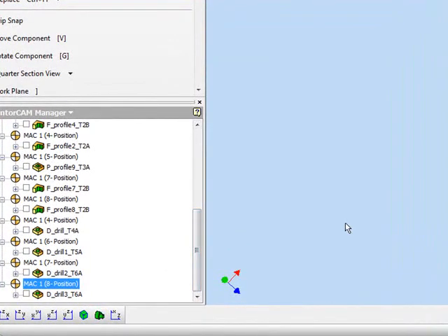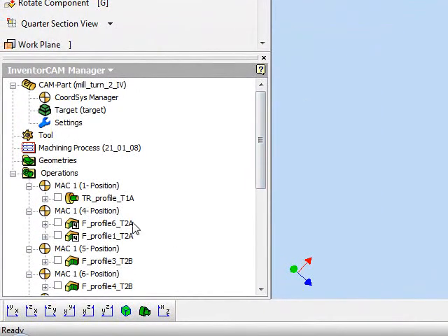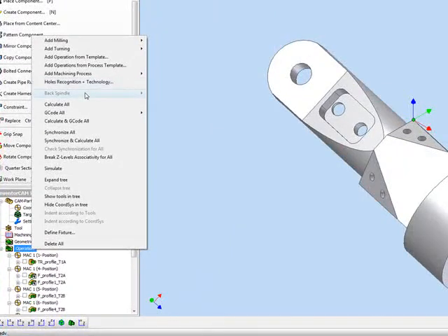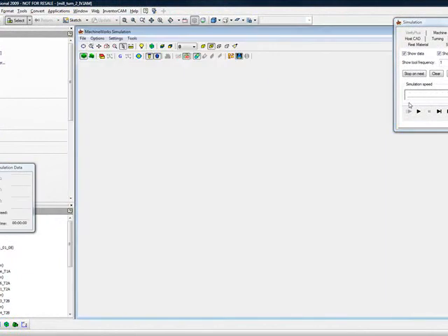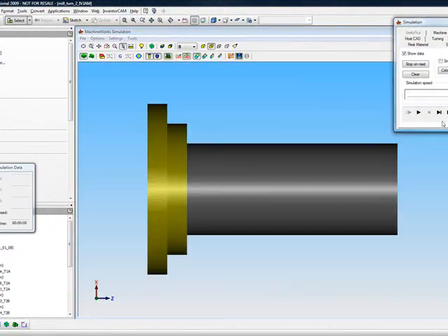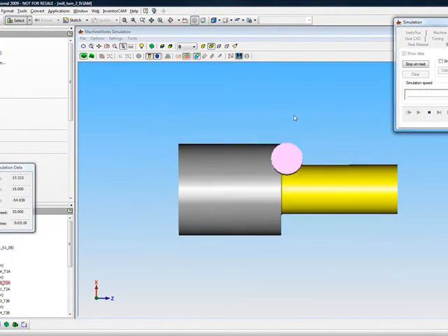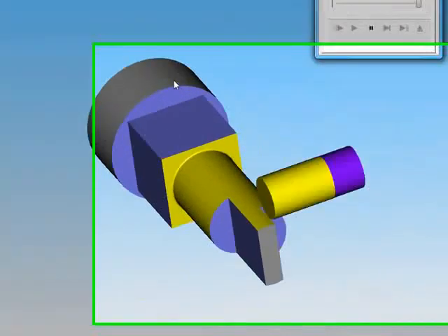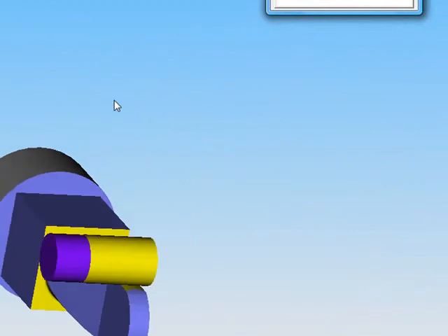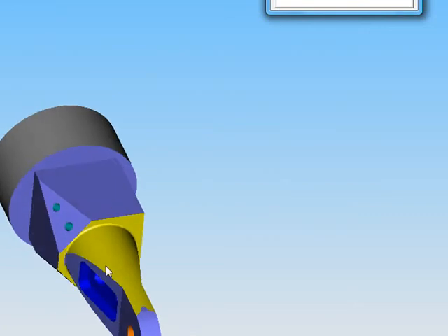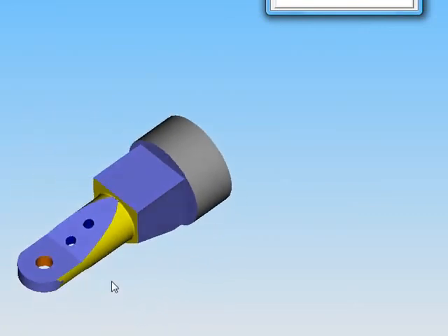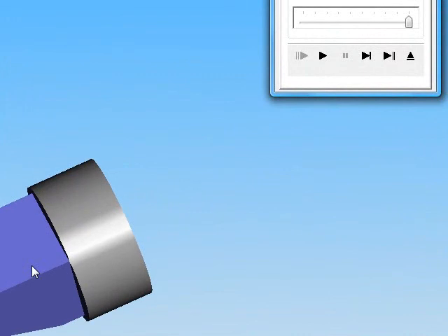And with all these operations, we've basically finished working on a part using MillTurn. If I do now the simulation on the entire part itself, and I'll use again the option of solid verify to show the simulation, we'll see that the tool is being turned, milled on all the sides, including this radius over here, the pocket, those edges, my drill points. Everything has been done to complete this part, and all this was done using MillTurn.